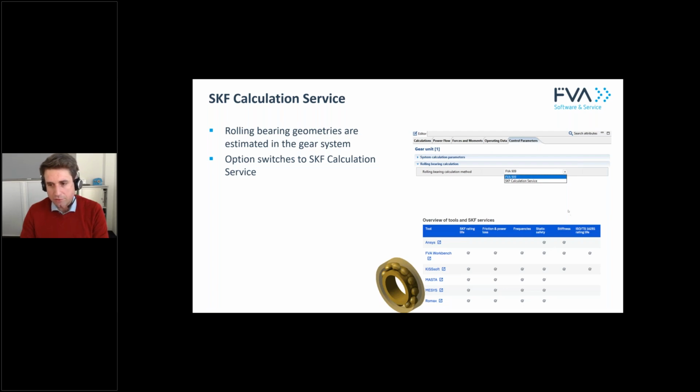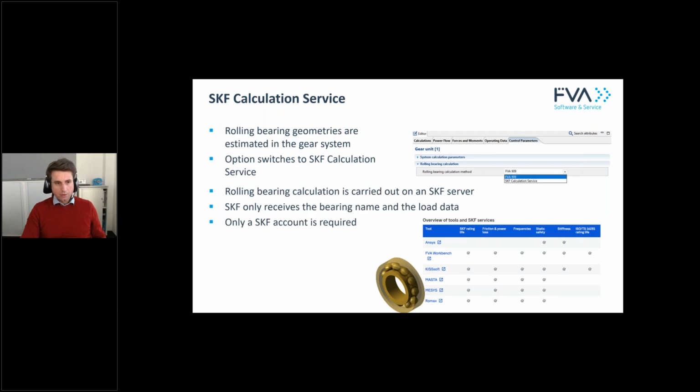The benefit of the SKF calculation service is that SKF is calculating on their service with the real geometry, including the profile of the rollers and also the oscillation for ball bearings. So you don't need to rely on our internal assumption of a certain geometry, but you could rely on the real geometry that SKF is providing.